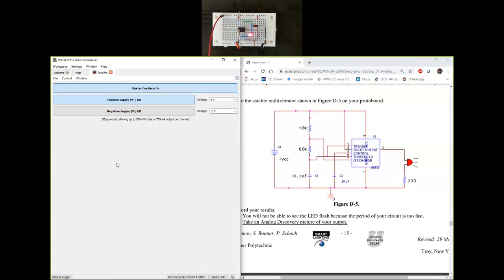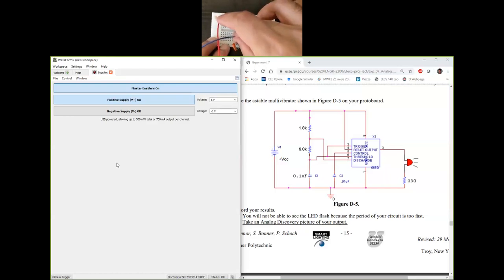So what I'll do is use an orange wire to measure the voltage, actually just the voltage output, pin 3. I've got an orange wire here. Let's say I use orange to monitor the voltage across pin 2 and pin 6, because they are both connected together. I want to see how the capacitor charges and discharges. So I'm going to place channel 1 on that, and channel 2, which is the blue wire here, I'm going to connect to the output of the timer, which is pin 3. So let's see.